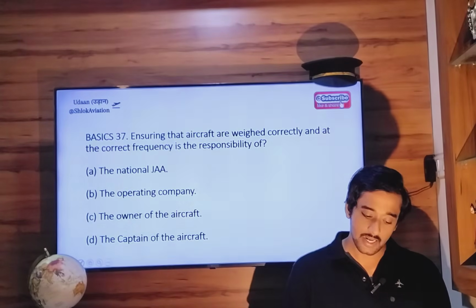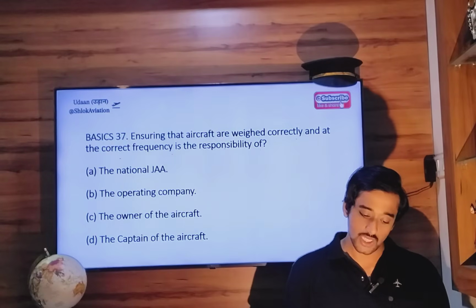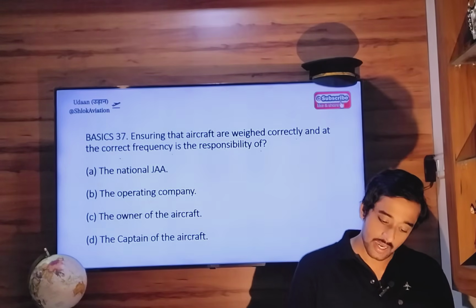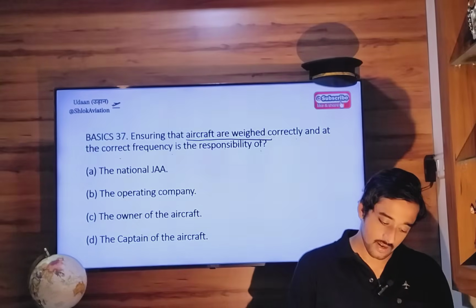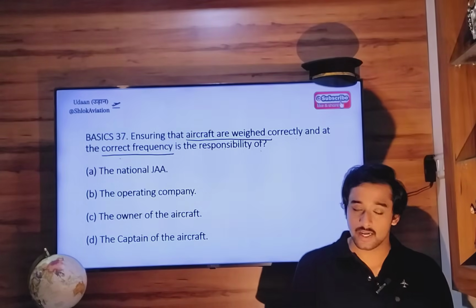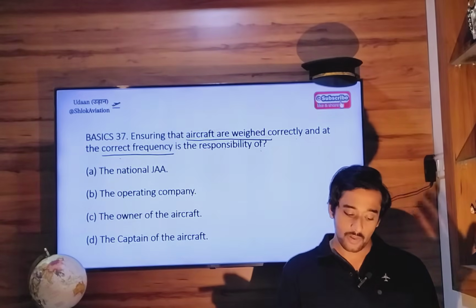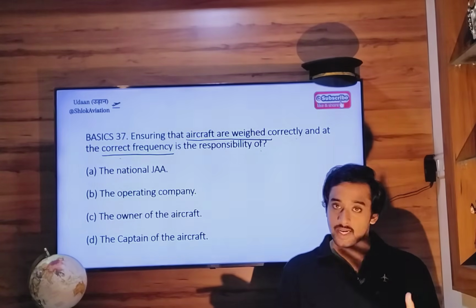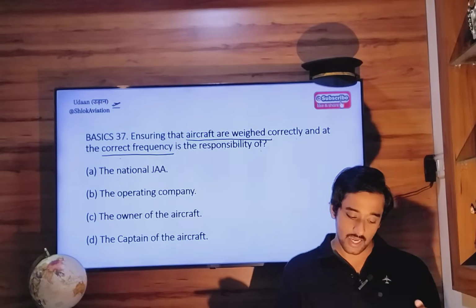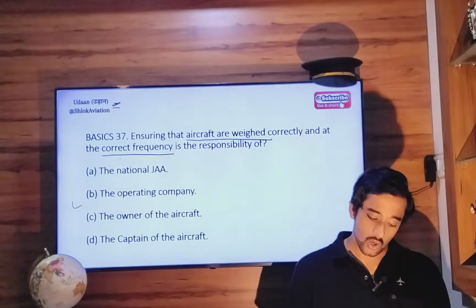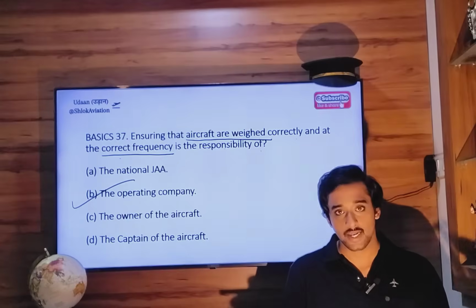37. Ensuring that aircraft are weighed correctly and at the correct frequency is the responsibility of whom? Okay, so the weighing of aircraft and the correct frequency of that is the responsibility of national authority like DGCA, operating company, owner of that aircraft, or captain of that aircraft. So correct answer is the operating company or the operator of that aircraft.